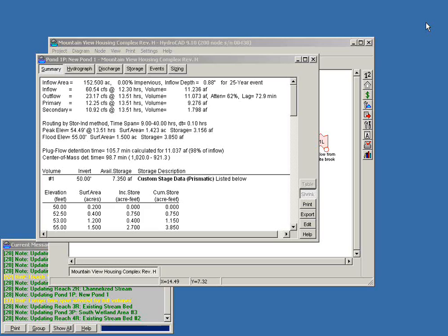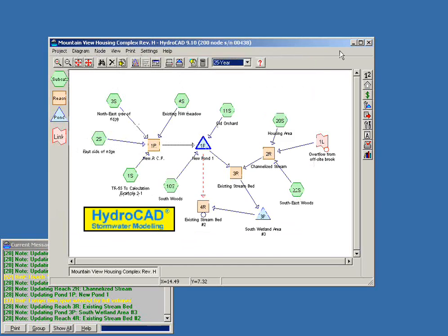The next capabilities I want to talk about are subsurface detention, retention, and infiltration. I started by talking about traditional detention ponds, which traditionally just detain the water. They retain the entire volume, and so the entire amount ends up being discharged from your site. There are, however, a number of techniques you can use to combine infiltration with your storage effects.